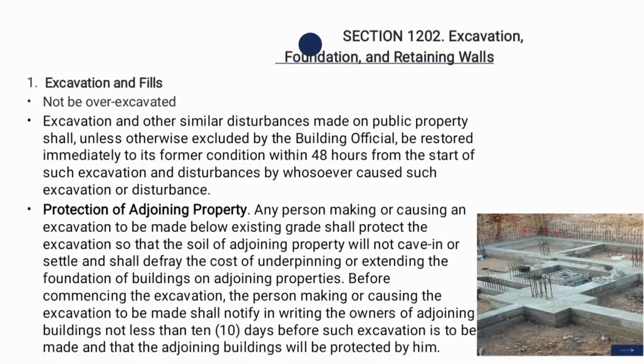And of course, before undertaking any excavation works or any drilling in the ground, the person who undertakes the excavation shall contact all of the public utilities for the safety of everyone, and of course for the safety also of the workers.